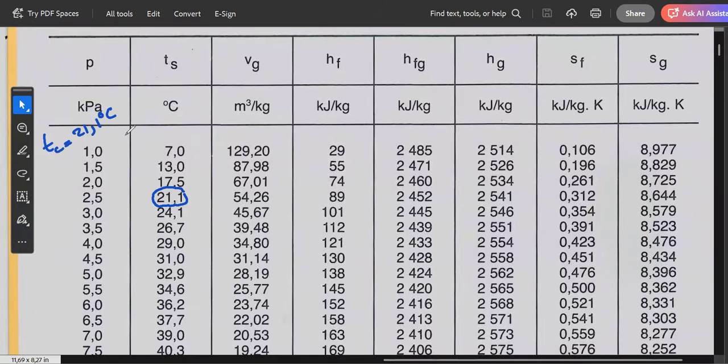I'm just saying. Therefore, you can go straightforward in your steam table and see that at that temperature of 21.1, HF, remember, it is the condensate, the liquid, so we talk about the enthalpy of the liquid. You take it directly as it is, because you have that value from the steam tables.